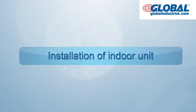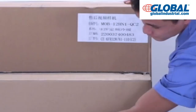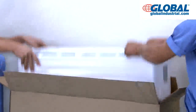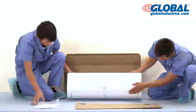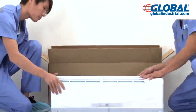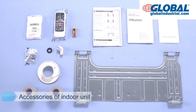Installation of indoor unit. Confirm whether the indoor unit matches the outdoor unit according to the model of purchased product. Unpack the packaging box, take out the indoor unit, and examine whether there is any scratch, deformation, and other defects on the panel. Take out the cardboard for installation. Take out the accessories. Check whether the accessories are complete.